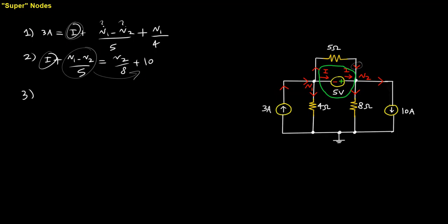So what we need is a third equation to be able to solve the system of equations. So what we do for that is we invoke Kirchhoff's voltage law, or KVL, to invoke some sort of physical law and solve the circuit. So how would you apply KVL here? Now, we're going to talk loops, not nodes. The likely loop of interest here is this loop, and the reason for that is it relates V1, the problematic supernode voltage, and V2 all in one loop. And so if you go ahead and write that equation, let's see what we get.